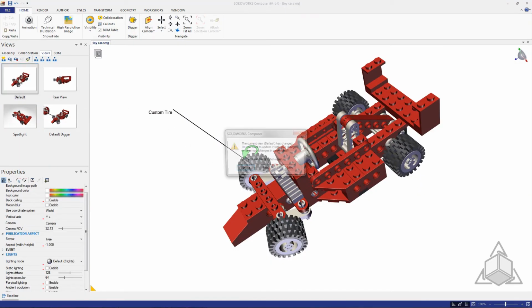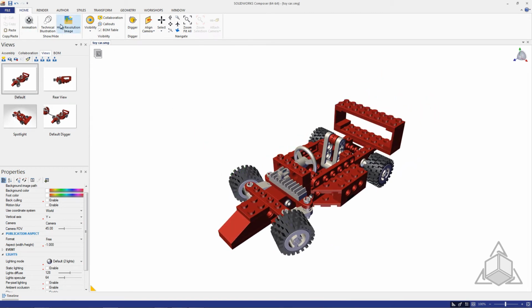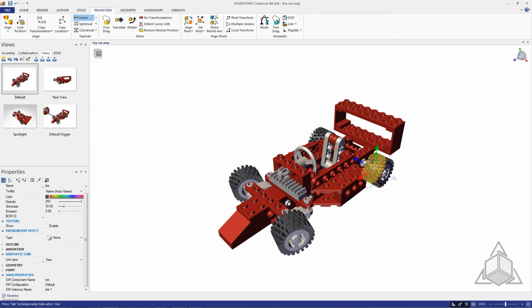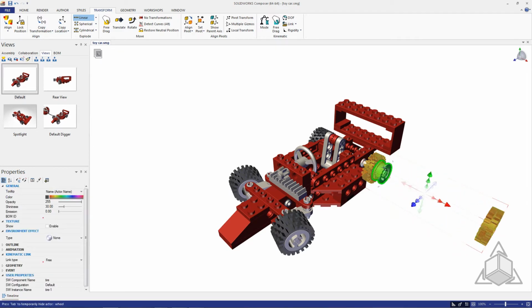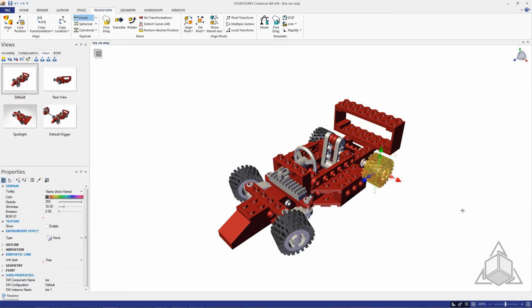All right. So let's go back into our default view. I'm not going to save that view. And let's talk about some of those linear options. If I click linear and click some of my selections here, I'm going to have to control select. And as I drag them out, you can see that they do space. Now, I have to have more than one thing selected to then adjust, because it leaves one thing exactly where you are.